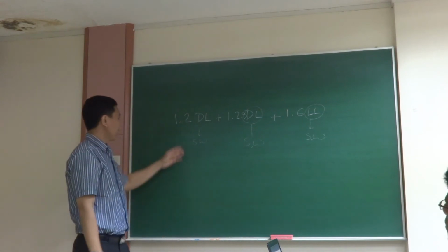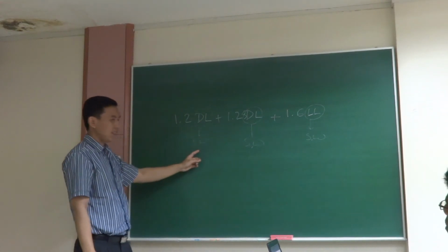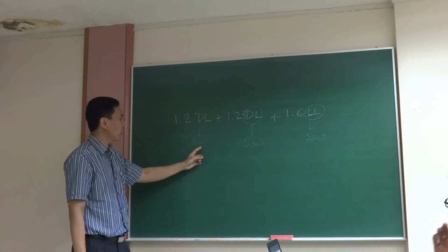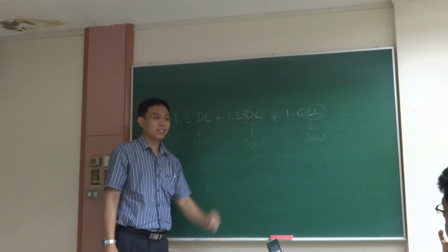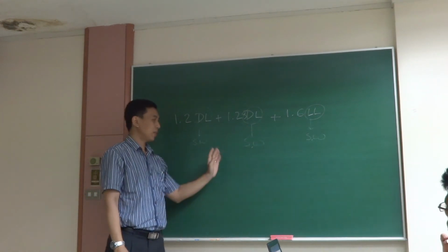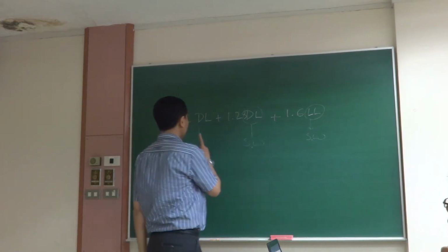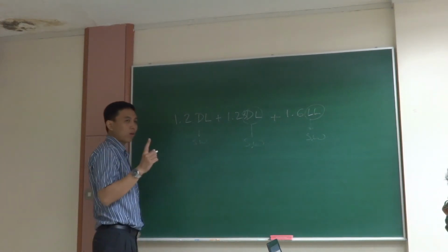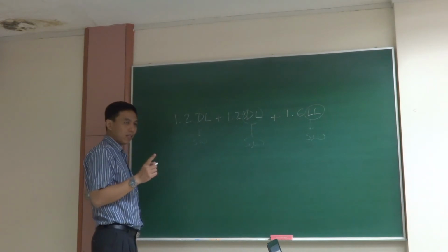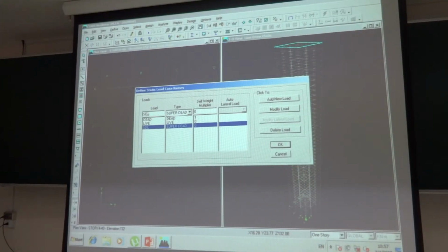So in your load combination, you are considering the self-weight of that beam 3 times, which we do not consider. So you have to use the self-weight multiplier only for one load case. Okay. So this is for gravity loading,